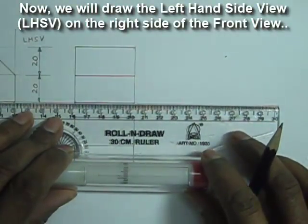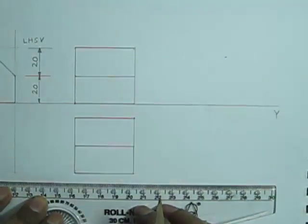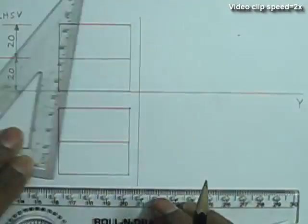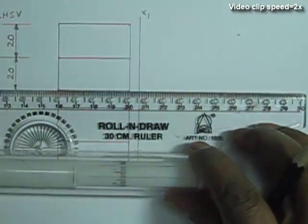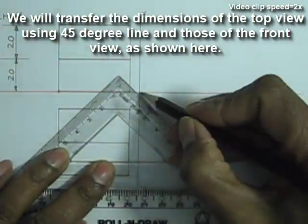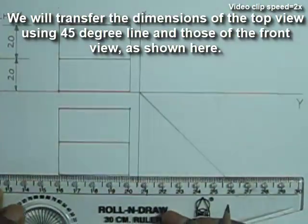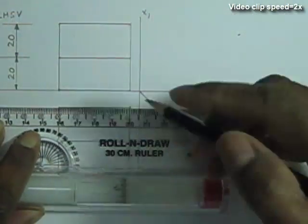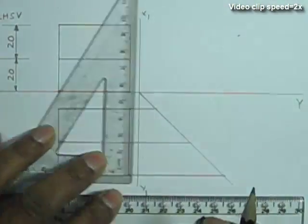Now we will draw the left hand side view using the 45-degree angle line. We will transfer the dimensions of the top view using the 45-degree line and those of the front view. These are construction lines, so they should be drawn as thin lines.